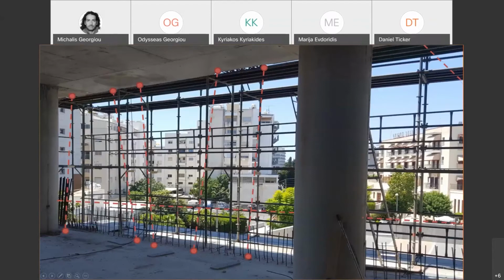To be more clear, instead of trying to set out the formwork in 3D from the exterior or the interior, which is a very difficult process and sometimes not that accurate, we combined these two methods by setting out the plan, the floor and the ceiling, and then interconnected these dots in order to generate a puzzle-like structure for the formwork engineers to place the formwork against.